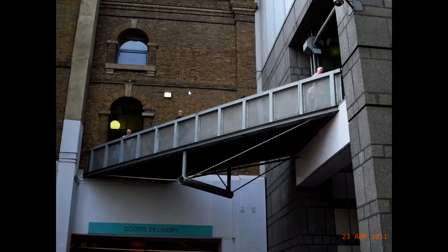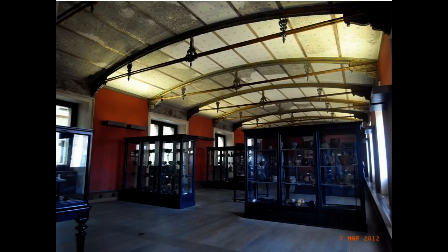Here's another version of it. This is by Charing Cross Station. In this case the handrail, if you like, is not structural. It's just stopping people falling off the edge. The beam that's spanning is just that. That's all it is. So that's pure tension, pure compression, and that's just connecting the two sides. Effectively, there's a truss on one side, there's a truss on the other side, and that's just connecting the two of them. So that's a very elegant and lightweight way of building trusses.